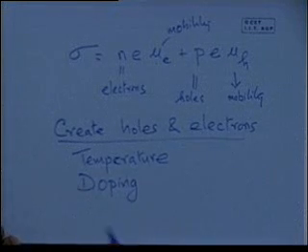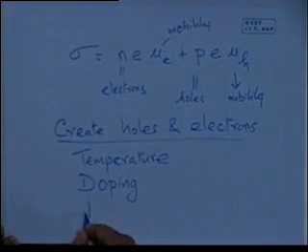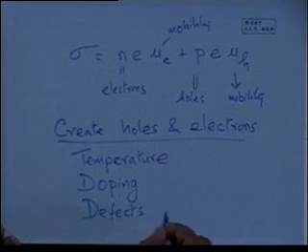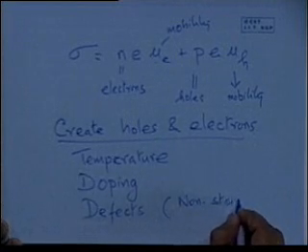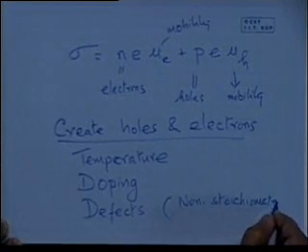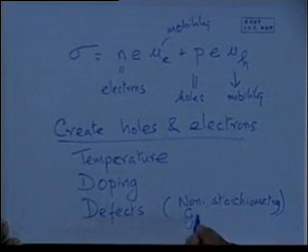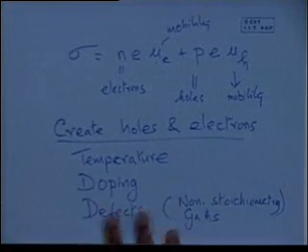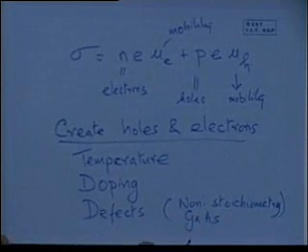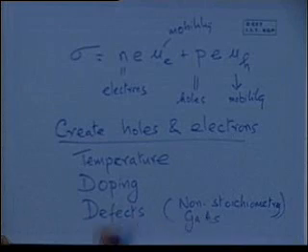I put in other kinds of materials in here and dope it. Or through defects. What kind of defects? Say, non-stoichiometry. I have a compound. Instead of having equal numbers, for example, suppose I have gallium arsenide. For a stoichiometric gallium arsenide compound, there's one atom of gallium and one atom of arsenic, all through. But let's say due to some processing problem or technique, I have fewer arsenic atoms, arsenic evaporated. Now I've got more gallium in there, resulting in a charge imbalance. Okay, that results in the formation of these kind of extra carriers.